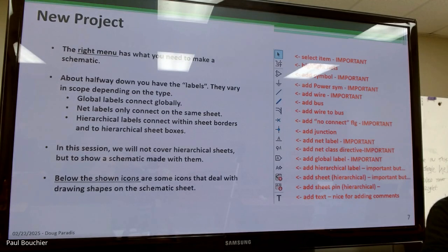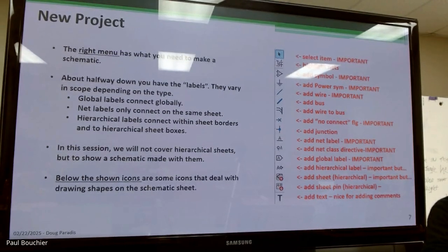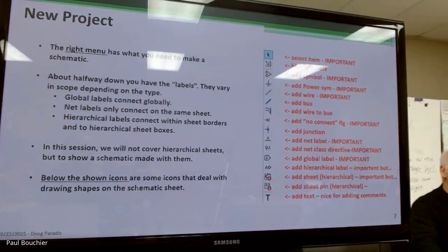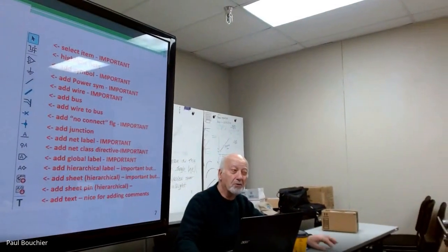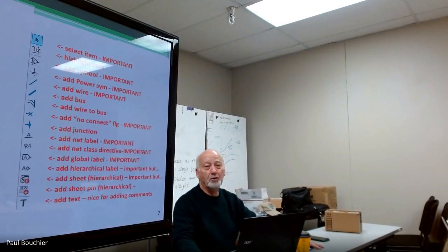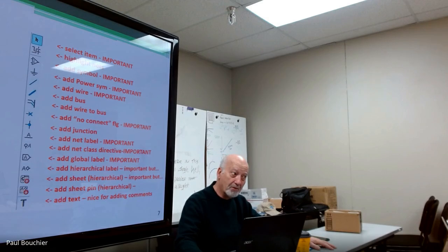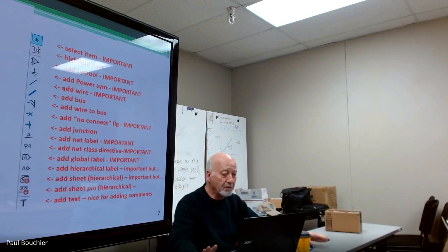So I'll ask the question. How many of you have ever had a PCB fabbed and it had a wiring mistake? But did you do it because you had an error in your ERC, or because you had a schematic mistake? A bonehead mistake, yeah, that's usually it. And then when you make PCBs, putting on the wrong footprint, that's the other biggie. But we won't go there yet.